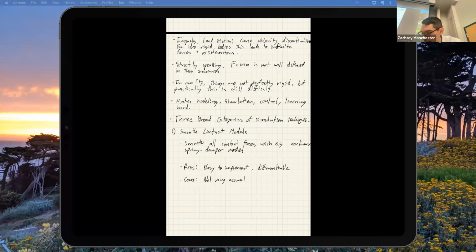And when I say accurate, specifically, we're talking about the contact dynamics. You could have a very, very fancy, sophisticated high order integrator, but when you're doing this kind of stuff on the contact forces, you're going to get interpenetration. So you'll get the robot's foot sinking into the ground several centimeters, things like that. And you'll also get creep. So you get interpenetration, you'll get force at a distance. So you'll get forces off the ground before the foot touches the ground. You'll get sinking into the ground.